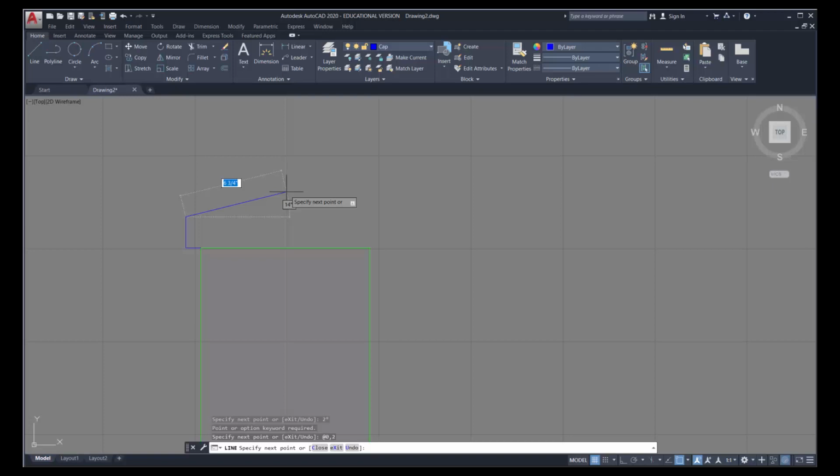That top is 13 inches, 1 foot 1. Divide that in half and you get 6.5 inches. So here we're going to type in 6.5, 2. That is half the width and the height. Now we're going to go down in the other direction, which is 6.5, -2. And then we're going to go straight down 2. So 2, -2. Now in the drawing, the blue line goes right across. So let's just go right to the opposite end. Press enter.